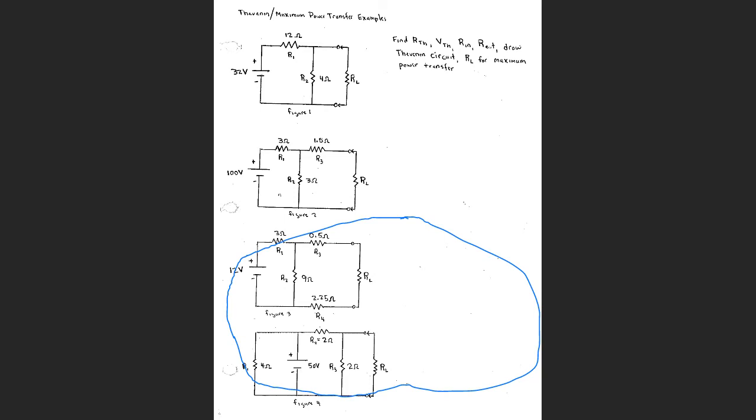A resistor just hanging there with no current going through it, you can mentally replace that with a piece of wire, which means connecting up here is like connecting here. So if I can find the voltage drop across R2, I got it. And I don't even have to use the voltage divider rule for that because I got this series circuit in here. I got 3 ohms and 3 ohms, so each one's going to drop the same amount of voltage. So since I got 100 volts, each one's going to get half. I want to have 50 volts across R2. Therefore, my open terminal voltage is 50 volts. So whoever got this, you're 100% correct.